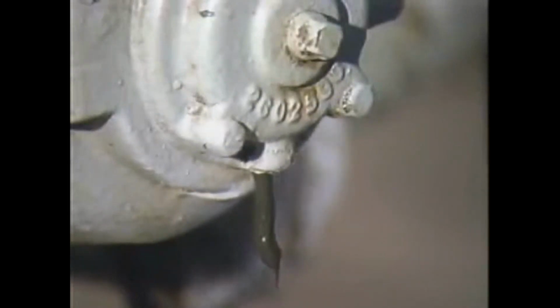Anti-friction bearings often have housings that retain grease and help keep out dirt. But a problem can occur if too much grease is put into the bearing, because there's no place for the excess grease to go. Consequently, a way for old grease to leave the bearing must be provided. In this example, the housing has a drain hole.